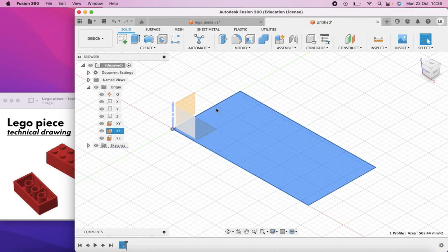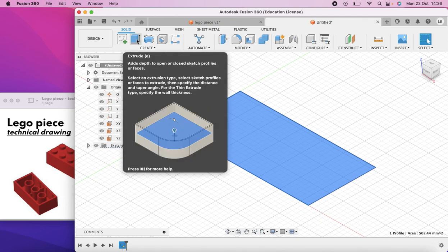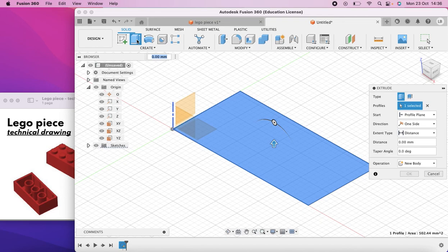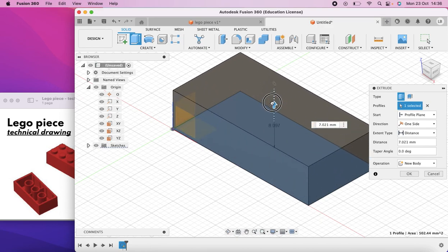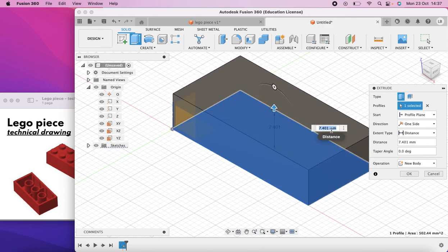Once I have clicked on the sketch, I'm going to click on the one that says extrude. The image that is appearing shows we have a sketch and it will create certain volume. So I click on it, and I have an option. One is to just drag this to wherever. Or I can simply, once again, use the numbers right here highlighted.